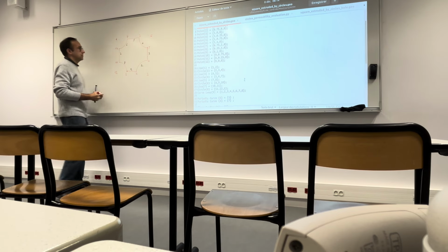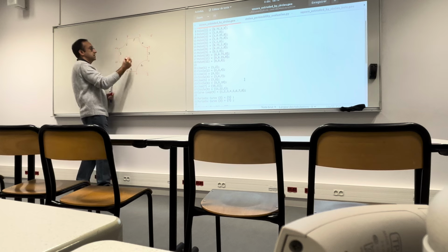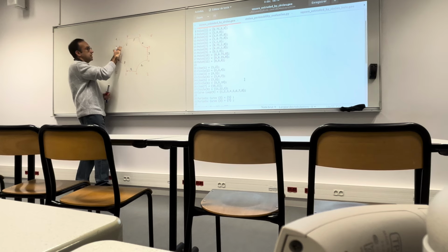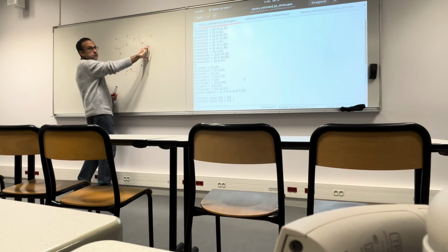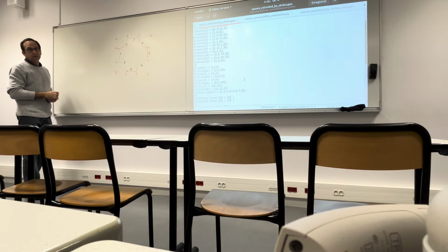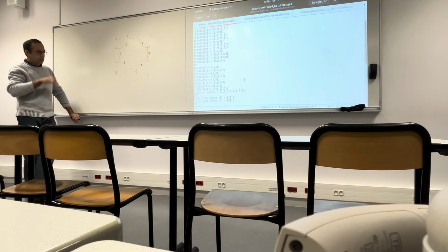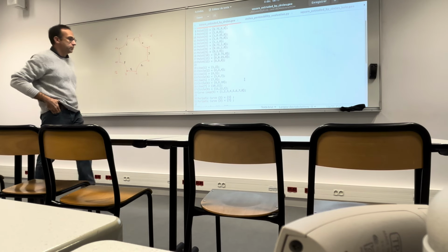Because obviously we want to impose periodicity conditions, but if the discretization is such that here you have not the same number of nodes as there, you are breaking, just because of your discretization procedure, the periodicity that you want to impose.